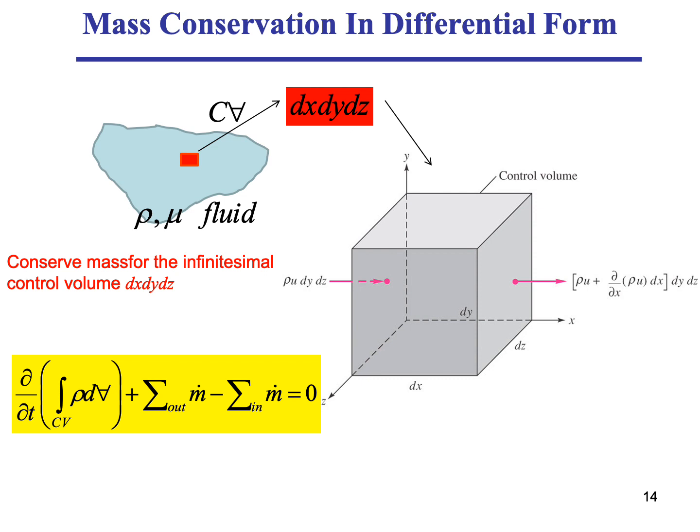So now this is our control volume, and we have, as we said, velocities coming in and leaving, and we can use our mass conservation equation for a control volume. This is still a control volume, albeit it's very tiny. The rate of change of mass inside the control volume is equal to the net fluxes of mass in minus out of the control volume. So we will start with the fluxes of mass coming in and out of the control volume.